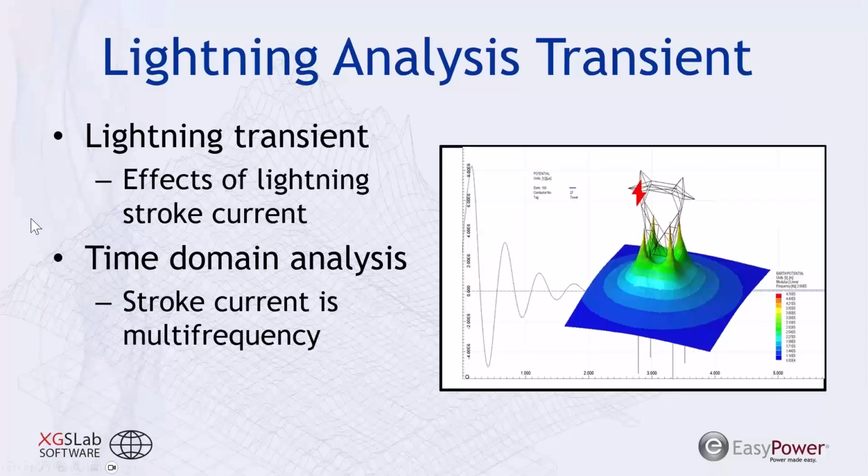with that as well. So we can model such things like a transmission line, see the stroke current propagating down from our shield wire as it goes down to the earth. And this little illustration indicates the ground potential rise that we see, or the Earth's surface potential, as the ground rods around that lattice tower are dispersing that current into the Earth.